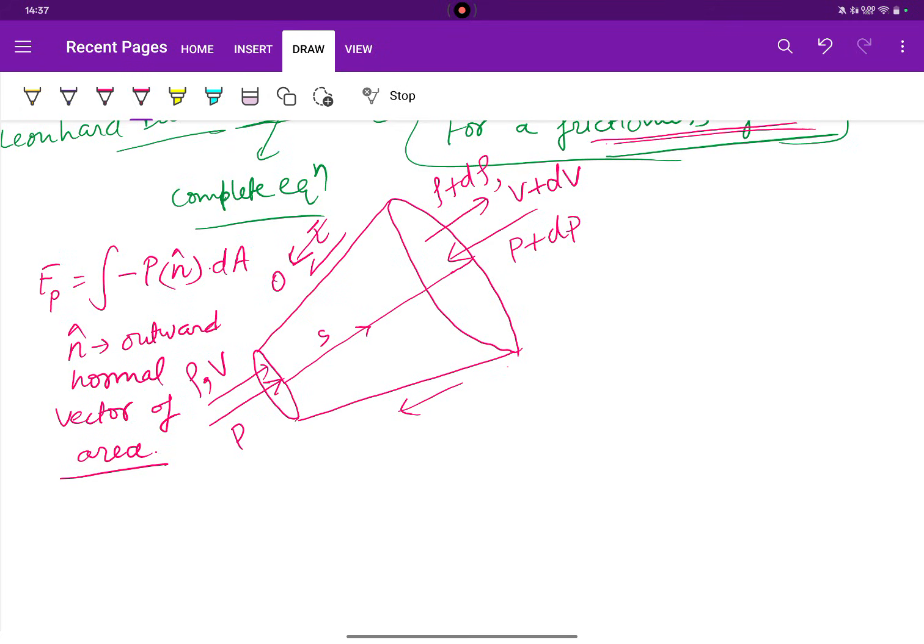Okay, and we have assumed this is theta, and this is dz. If we are considering an area element, basically dA, then along this is ds, and this is the direction s, and d theta. Now, just because I'm explaining this figure, I can have the gravity body force, basically the weight of this fluid element, and what would that be? Rho g into the elemental volume.